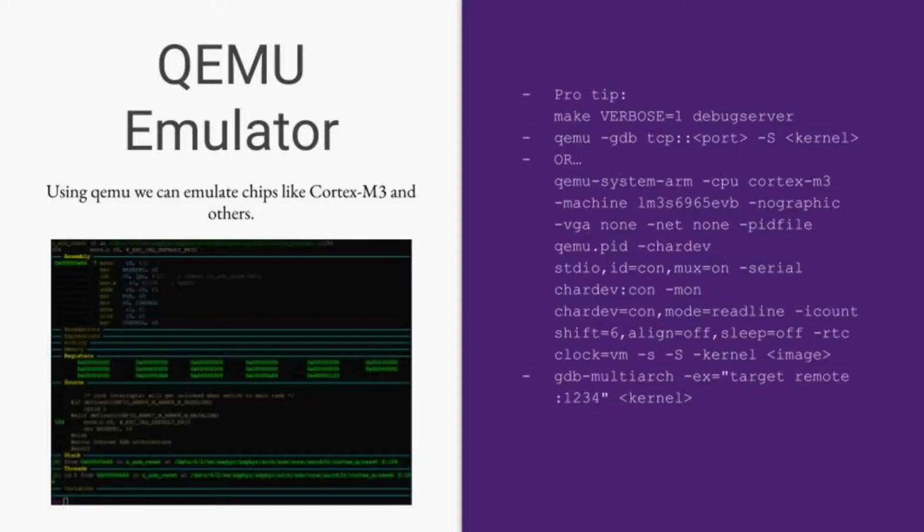But if you are debugging an embedded application, then the way it typically works is that you have a GDB server to which GDB then connects and can inspect the CPU registers and all the details of the hardware and display that to you as a user, right?